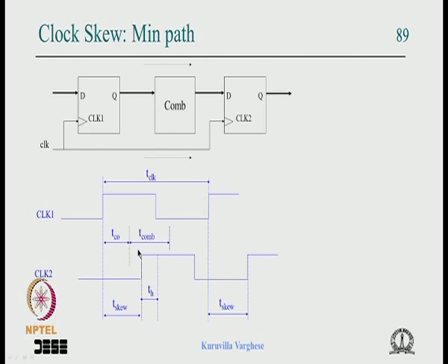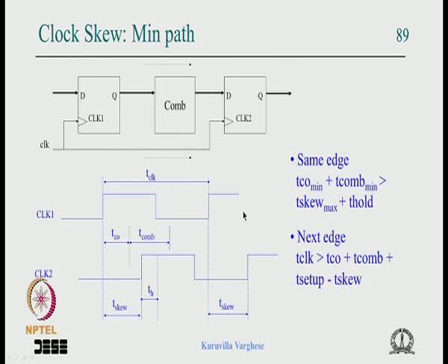In this case, for the register to register path from one clock edge to the next clock edge, we are in a better position because you have T clock plus T skew as the time available to accommodate this path delay. So if you analyze from one edge to the next edge, things look pretty comfortable, because that is easier on the budget. If you had fixed the clock period, then here is a relaxation on the clock period, which is good in a way.